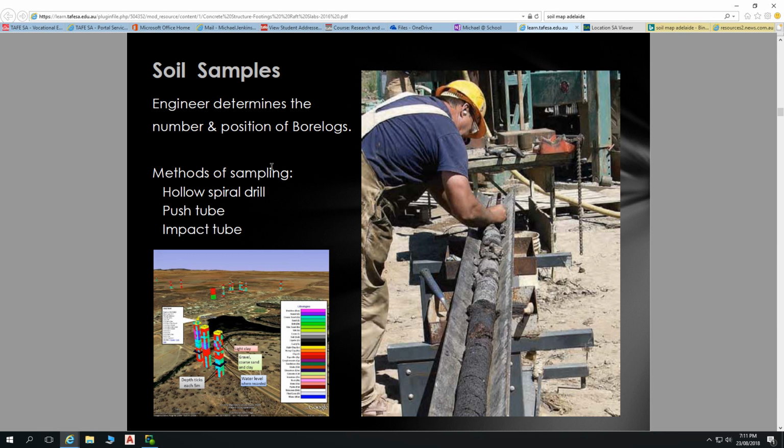That's a soil sample taken out of the ground. Now that's not typical for your residential architecture. Typically your soil sample is done on site, done with a hollow drill on the back of a Land Cruiser. They come out to be about this size, 30 mil or so, out of maybe that one's called a push tube, I don't know, but it's a big stainless steel thing that gets turned and it gets pushed down into the ground to sample soil.